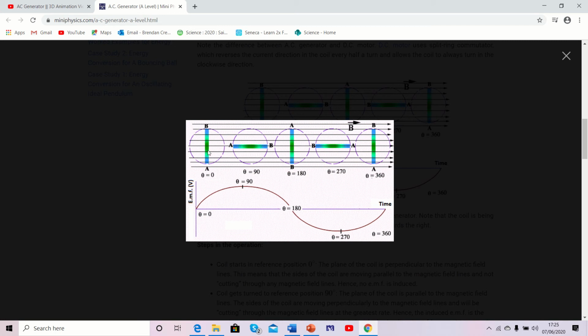If you look here, the colored line between A and B, that is the position of the coil. Here it's vertical. The purple dashed line indicates the path the edge of the coil will follow as it rotates, a complete circle. If we look at the arc of the circle in position B, that distance there, follow the pointer, you can see it is cutting just one magnetic field line. The coil in the horizontal position, this one here, if we do the same arc, same distance of that circle traveled, you can see it cuts a lot more magnetic field lines.